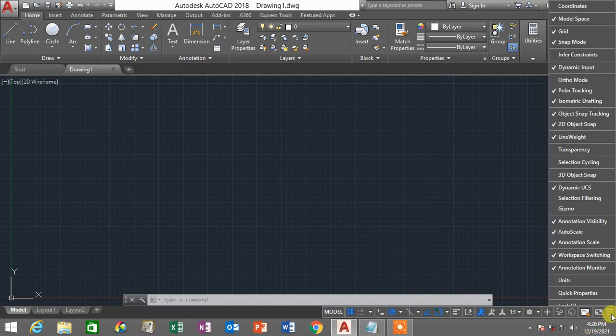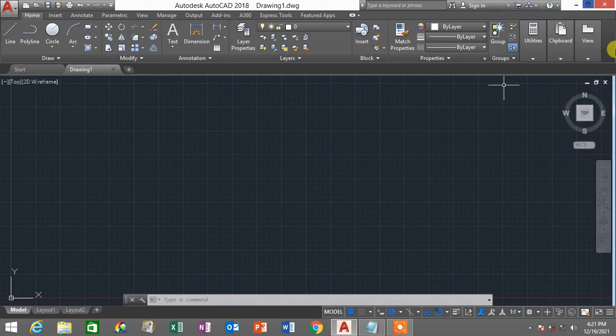So this particular icon, which calls the customization list button, controls whichever functions you want to include in the activation status bar down here. Just make sure all of these functions are ticked, and you can just tick it to choose so that it is going to be listed down here. So I'm going to click that button again, just to minimize the customization list button.